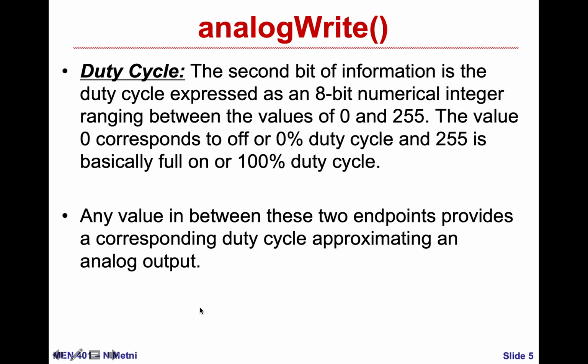As for the duty cycle, we know that in reality it is between 0% and 100%. But here I should specify it on 8 bits, so the duty cycle I feed my function is a value between 0 and 255.